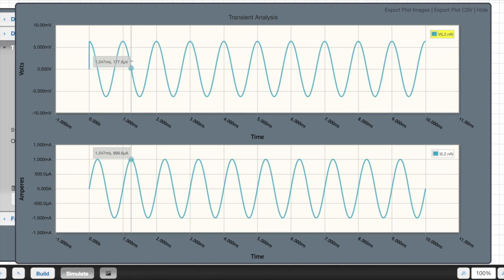And so what happens is that because the voltage and current are out of phase, certain devices may have sufficient voltage to begin operating, but then there's not enough current supply. Or at the times where there's a lot of current supply, the voltage potential is not there for the device to begin operating. And for things like electric motors, this can cause a lot of inefficiencies and overwork the systems, and they may not even operate.